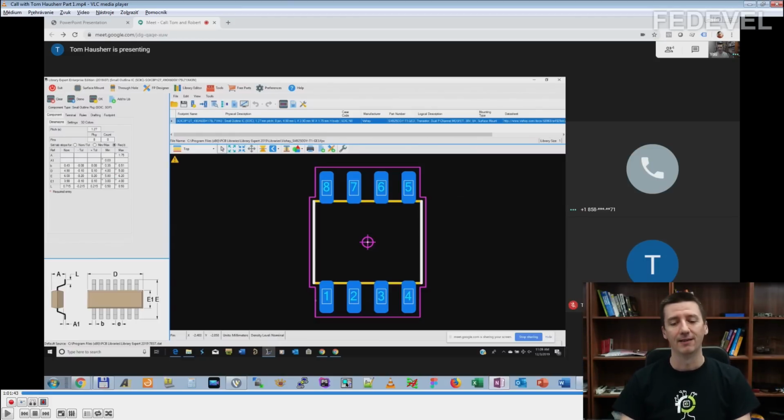Miracle. Yeah. And I would like to say, for good soldering, use a microscope. Once you solder under a microscope, or if you inspect your soldering with a microscope or with something that zooms in, then you will see if your soldering is good or not. And that will help you a lot. Just buy a good microscope.